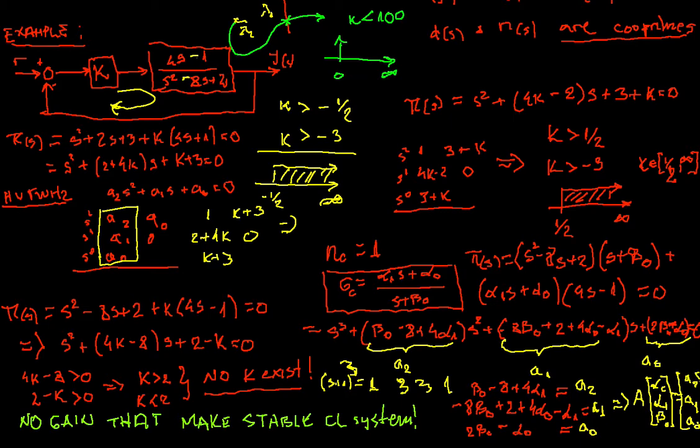In this way we're just solving the system of linear equations, and this system is trivially solvable for us. In other words, in the case when we could not stabilize with a gain, we had to increase the order of the controller to provide the new set of parameters given here, such that we can guarantee the closed loop system stability. In general, this is the procedure that we always follow when we design the controller.